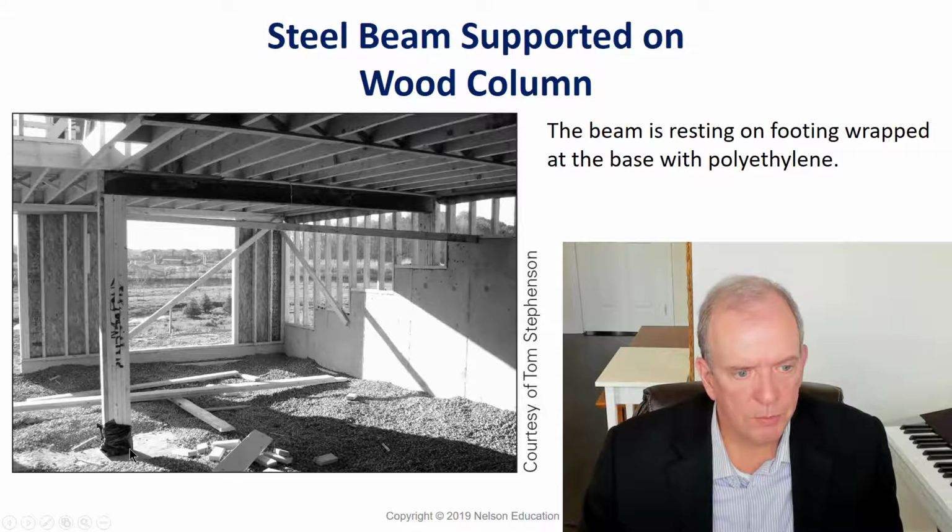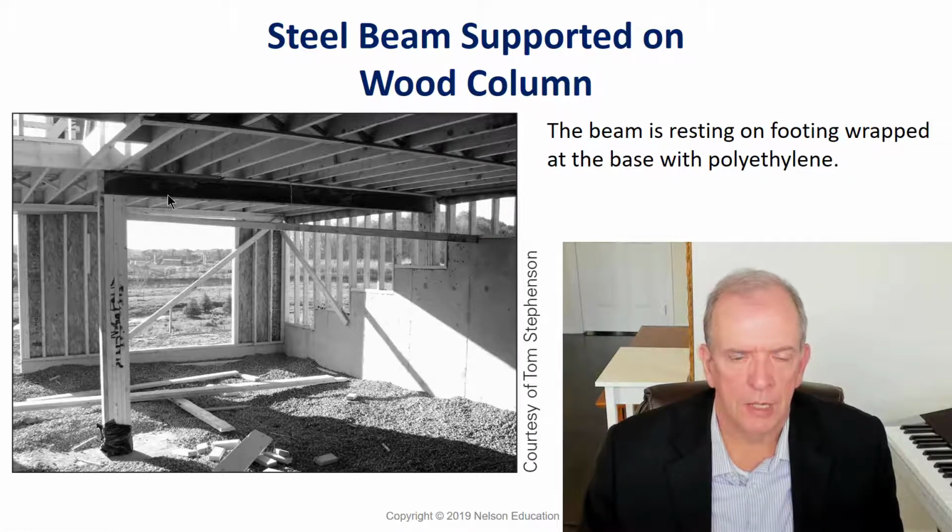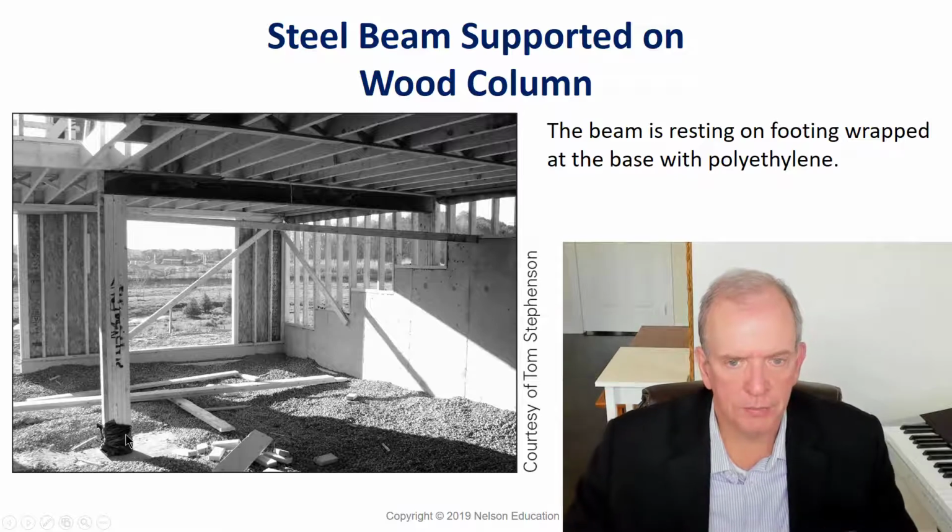This is covered around with plastic. It's resting on the footing. Wood columns can support steel beams as long as the steel beams are not carrying bricks or masonry construction. And this plastic is wrapped around because the concrete floor is going to be poured over top of this and on top of the footing. But the post should come down to the footing, not on top of the concrete slab, because then the slab will probably crack.